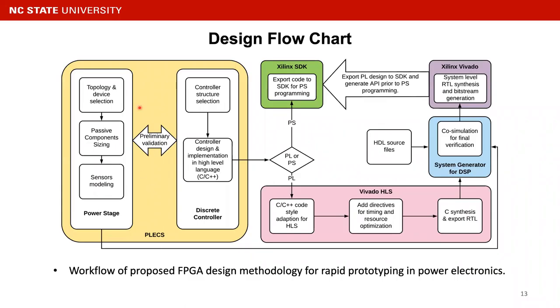And in Plex, usually we can first select our topology and the device, size the passive components, and also finalize the sensor selection. In the meantime, on the software side, we will finalize our controller structure, and also we can implement our control design in a discrete manner, like in a high-level language. So in this, we can run a preliminary round of validation in a pure software environment.